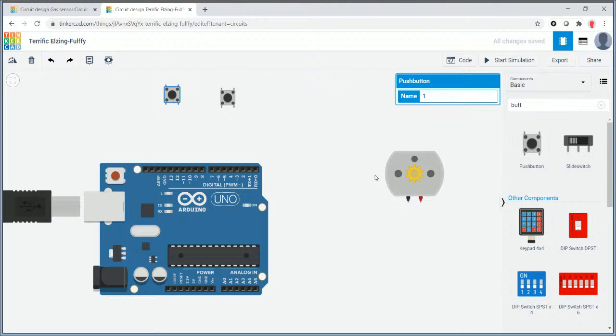Cool. So we'll first make the connections. Now we have to connect the DC motor across two pins, terminal 1 and terminal 2. Since the DC motor works on direct current, we can simply switch the polarities of this motor to make the motor turn in the opposite direction. So let's say we give terminal 1 as positive and terminal 2 as negative, the motor will turn anti-clockwise. And if we give terminal 2 as positive and terminal 1 negative, the motor will turn clockwise.